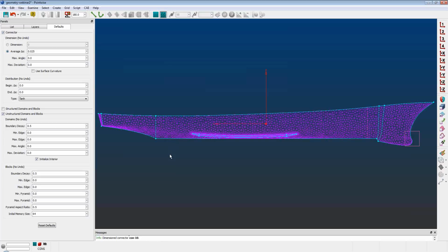The current release of Pointwise, 1604, has the 2D anisotropic meshing, so you can make T-Rex grids on surfaces with the current release, and we're working on the 3D anisotropic meshing for the next release. We're pretty early in the planning process, so I don't have an exact release date. Our goal is to get it out in 2011, and the sooner the better. Once we get far enough along to have an estimated release date, we'll let you know. But that is planned for the next version of Pointwise.